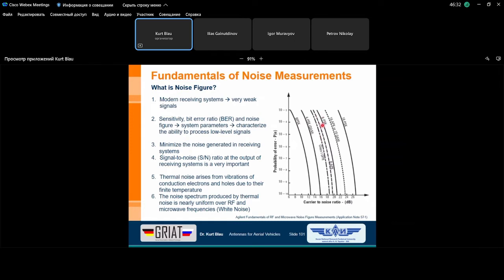so-called 8-PSK. Then we have 8 different phase states, which means every state has a 45 degree difference to the other state. And it's the same as here, but with smaller phase distance. In this case, 90 degree, and here 45 degree. And here we have the first scheme which also includes modulation in the magnitude.